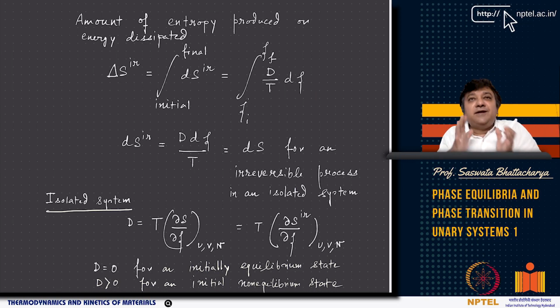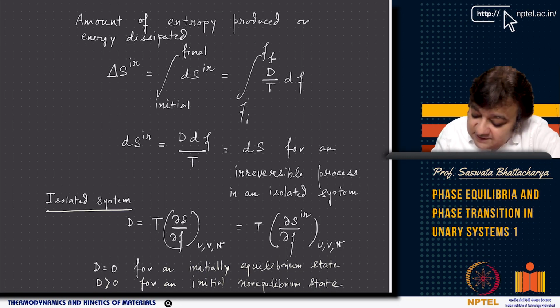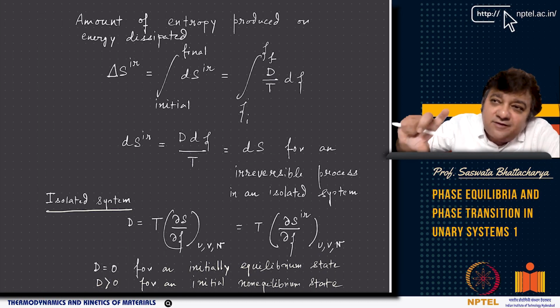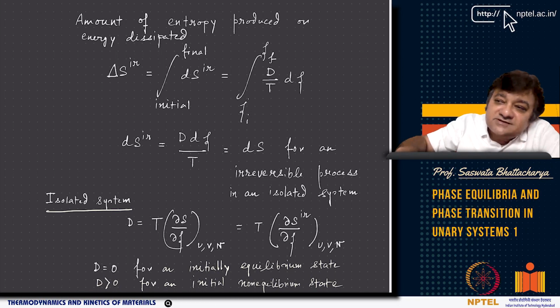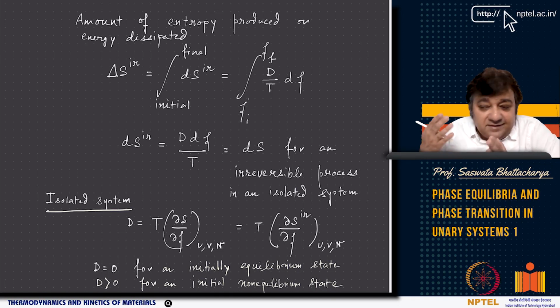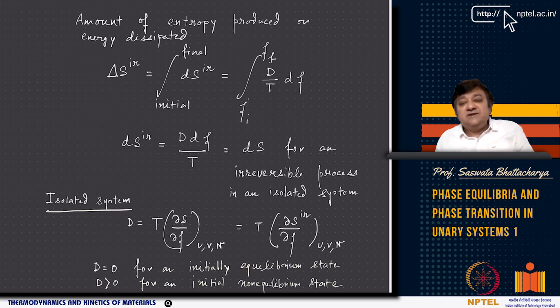When cubic and tetragonal phases are coexisting, the order parameter is between 0 and 1. When it completely becomes the product phase, that is the tetragonal phase, then zeta becomes equal to 1, otherwise zeta is equal to 0, right? So that's how you can define a cubic to tetragonal phase transition. It means a solid lattice is transforming from cubic phase. Cubic phase means it has a cubic crystal structure. Then at a certain critical temperature, for example, it changes from cubic crystal structure to a tetragonal crystal structure. It can be because of temperature, and it can also be because of the application of certain strain, that you get such a transformation.